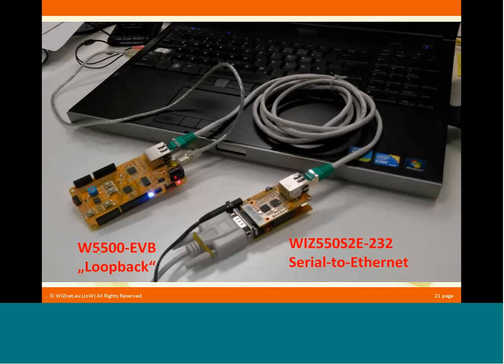This is a picture we took a few seconds ago from our desktop. I used a W5500 EVB, so that is our chip. That is also the NXP M0, and here USB, a serial interface, and here we have those serial Ethernet RS-232 connections, and we can transfer data in any direction you like. Here it's an Ethernet connection between those two, but I can also show you internet connectivity from the PC to the Internet and back into the module, out from the serial interface into the PC.